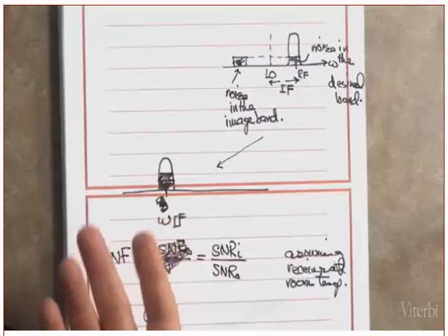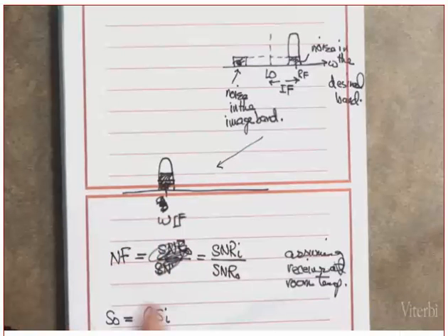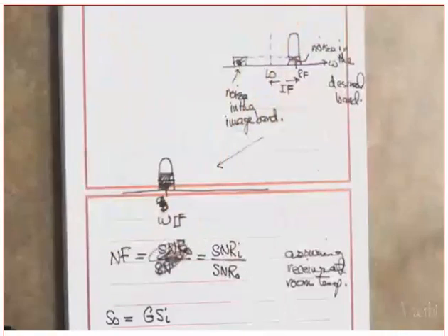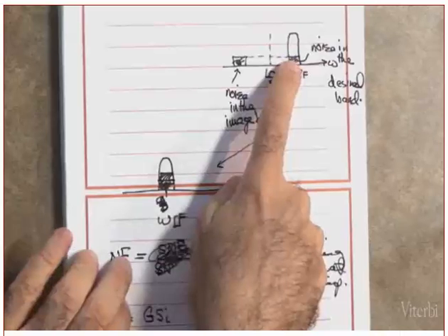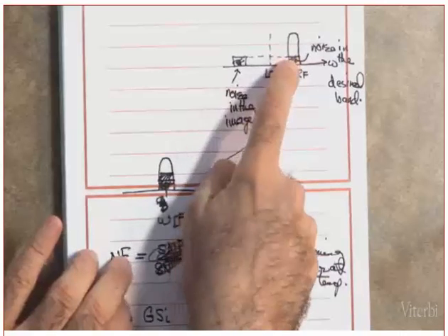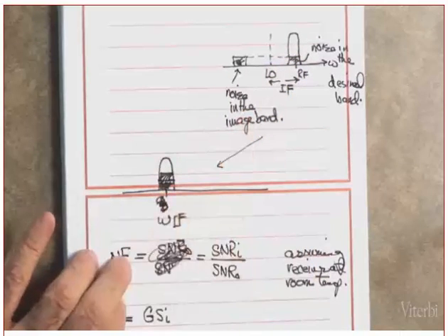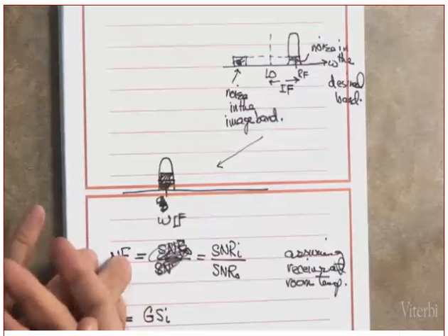Are you following me or not? Remember when we were talking about the noise from the ID, the drain current, and we saw that it does not depend on the frequency, in the previous set of charts. Do you remember this? The drain current does not depend on the frequency, which means it's white. If it is white, does it mean that there is a portion of the noise generated within the RF? Yes or no? Say something.